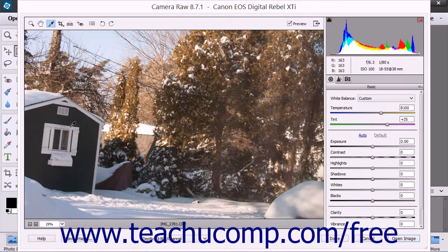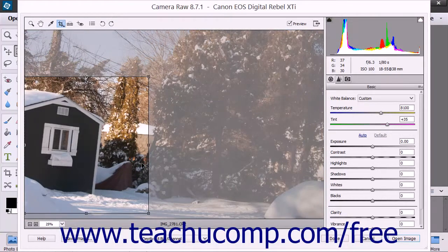You can use the Crop tool button to remove unwanted parts of an image. In its most basic use, you can click the Crop tool button to enable the tool, and then click and drag to draw a bounding box over the part of the preview image that you want to retain. Then click another tool within the Tools bar, or press the Enter key on your keyboard to finish cropping the preview image. However, you should also note that this tool has many other settings that you can apply.